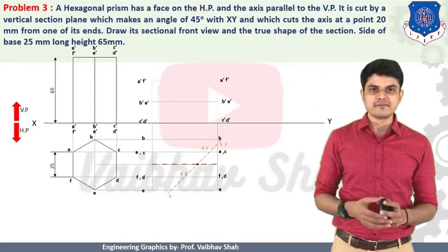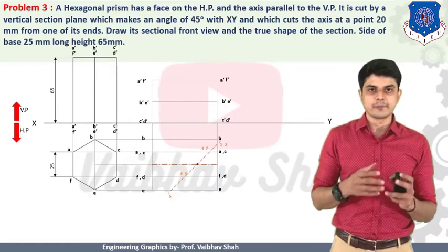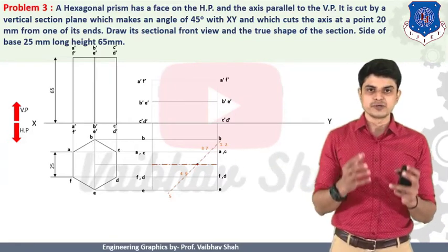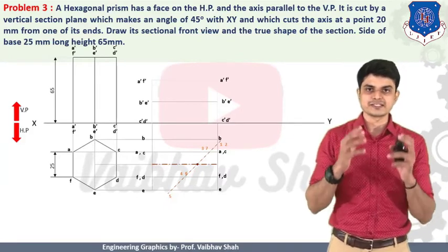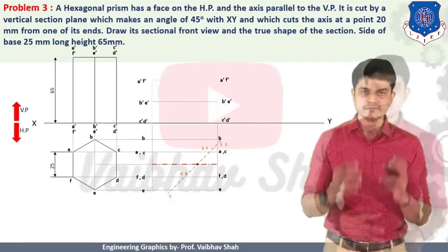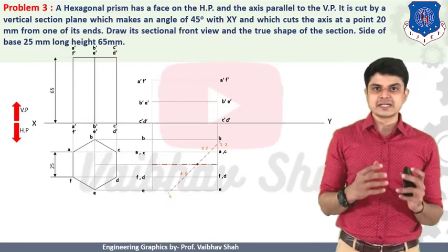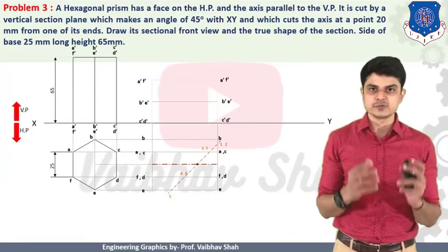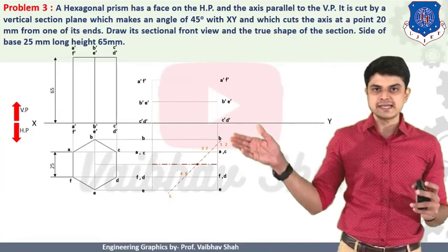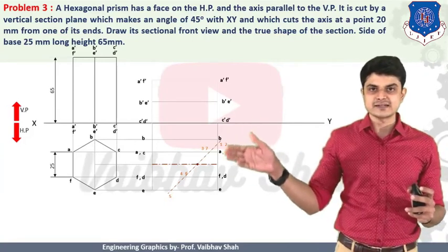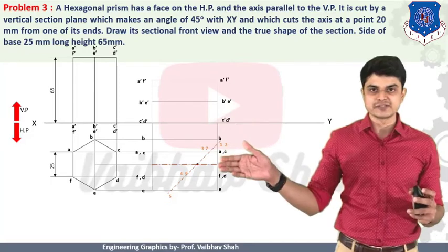Then after having this cutting plane line, we should have the points marked on this line. So you should remember how to mark these points. So let us see the procedure of how to mark these points on the cutting plane line. So now let us understand how I will mark these points on this cutting plane line. So we should start alphabetically first. We should start with this point. So first AB. So this line cuts this AB. So we should specify this point as 1.